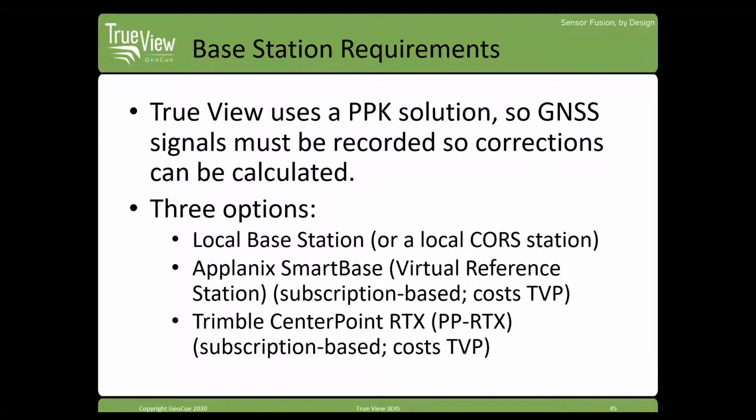So there are going to be three options for this. There's local base. This is a physical base station that's set up on site before the mission starts. That base is recording GNSS data during the entire flight, and it should be within 12 miles of the survey.